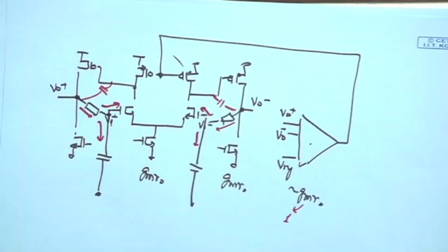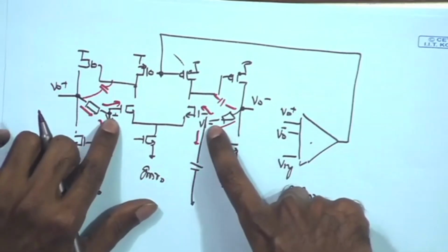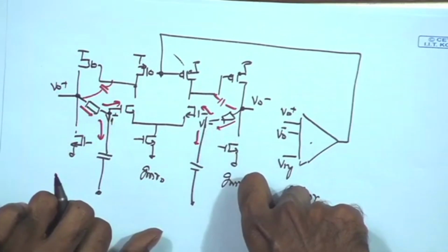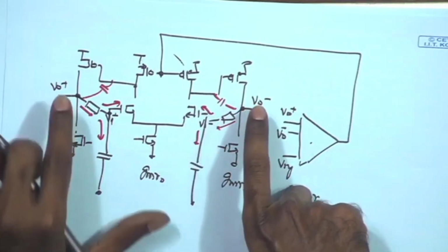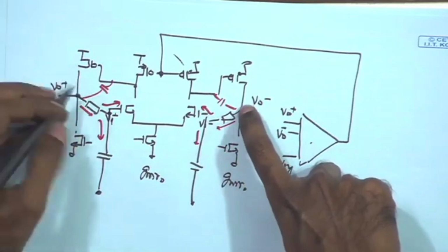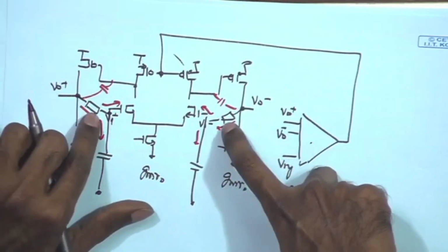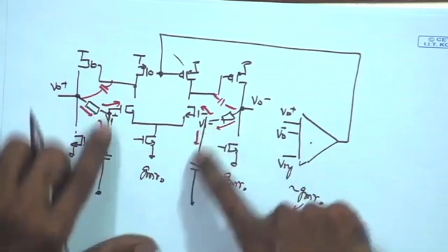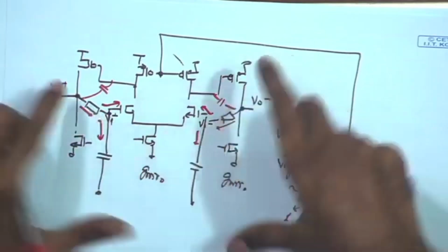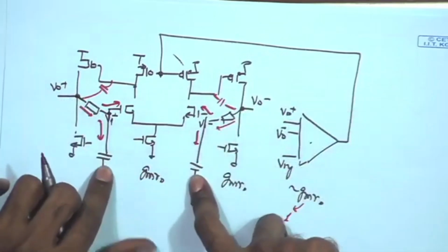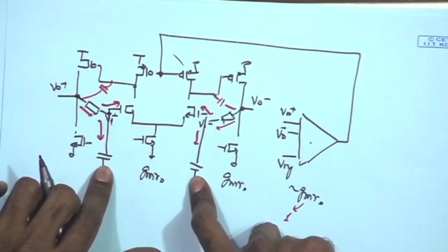In AC it will block. Because the output voltage can go to the input port also? No. For the DC response, once again, because we have a very large R value, and at the input side you have an impedance which is much smaller than the R. So if you take superposition, because of the output signal, there will be hardly any impact on the input side.